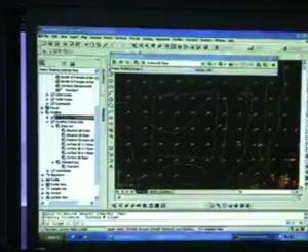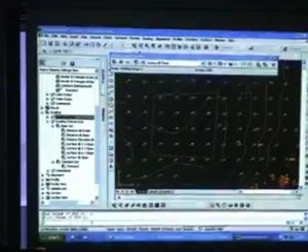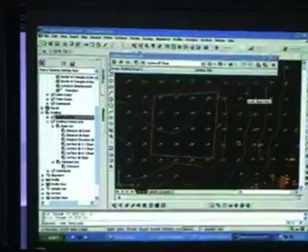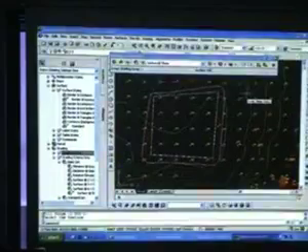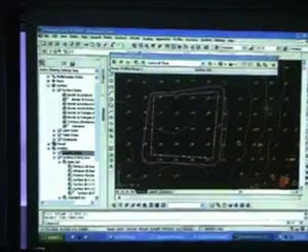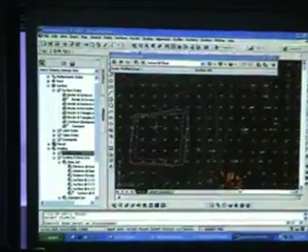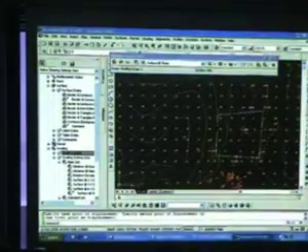And then they'll prompt you, okay, what is the cut slope? So let's say I put 1 to 1. Fill slope, say I want 2. And that's how they create the slopes. Now this command in Civil 3D is very good because it updates automatically as well. I'm just going to zoom out a bit so you can see. And I move this to a new location. Notice how the slopes also adjusted to the new location.